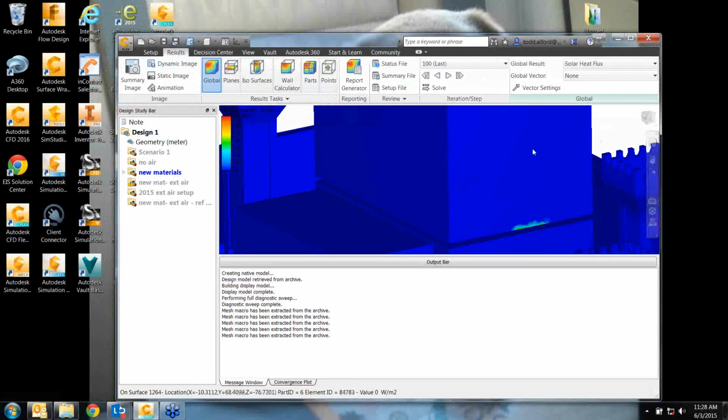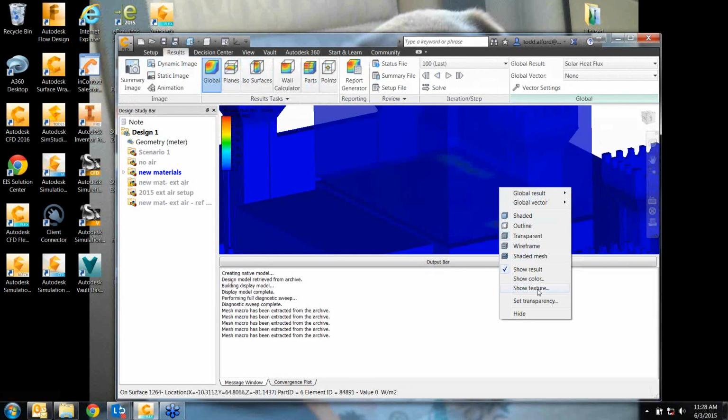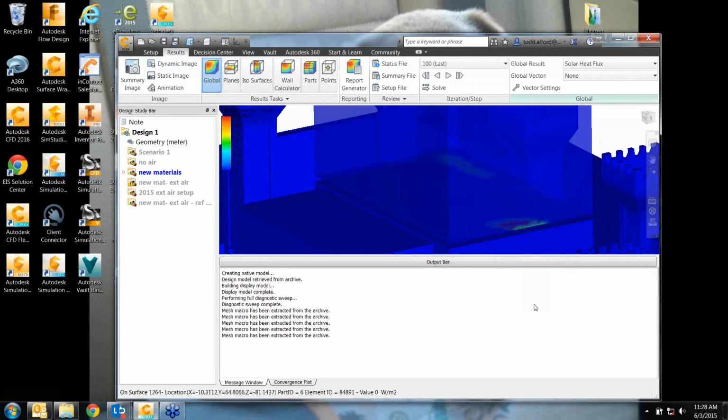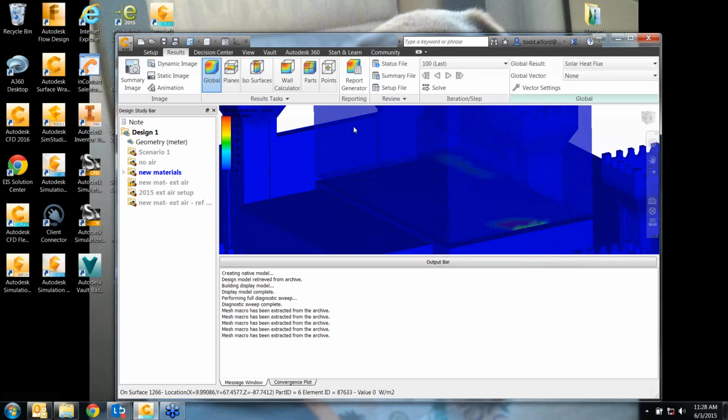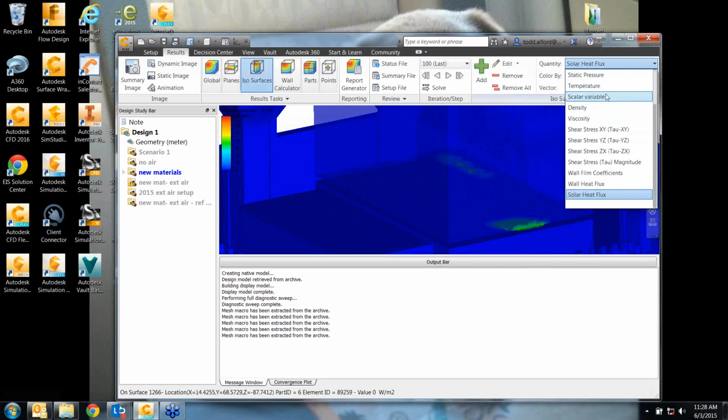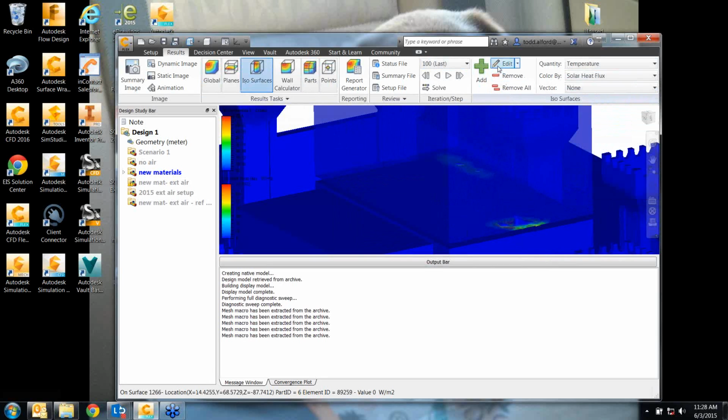The problem I see, though, that I guess I didn't think about before, I think it needs to be 2, because we have a 0 solar heat gain coefficient with the solar wall, so we're always absorbing all of the energy. But if we've got an 85% reflective wall and we really want to only absorb 15%, then I think what we need to do is have 2 sections.